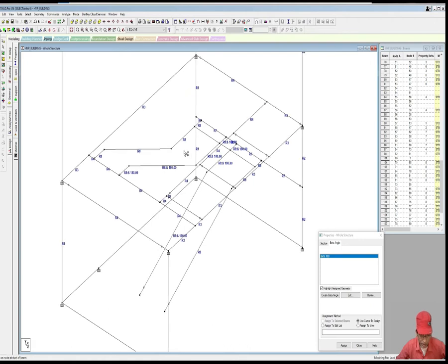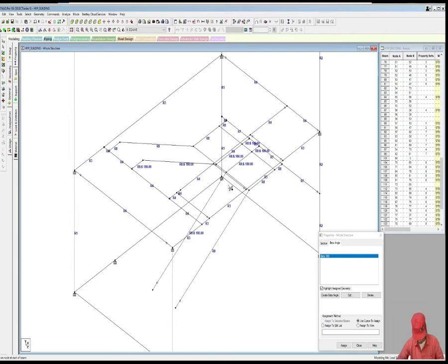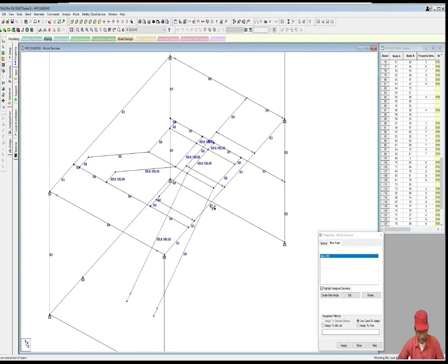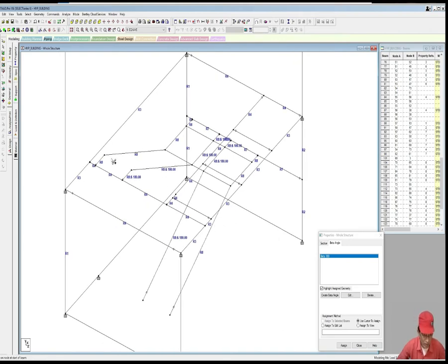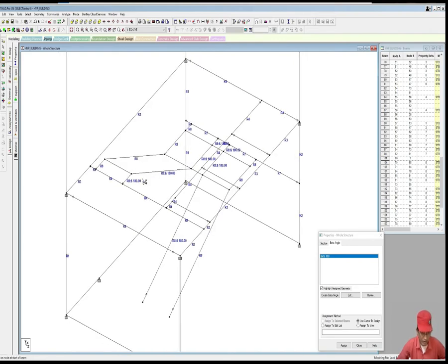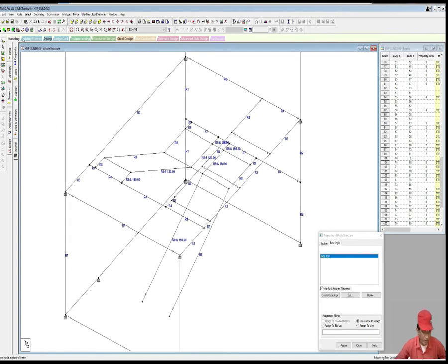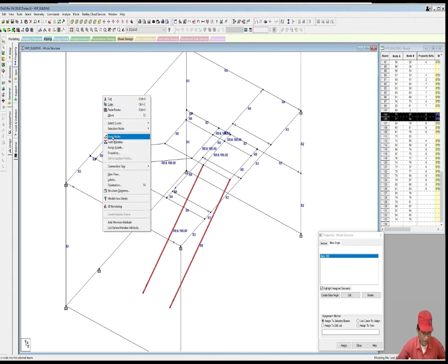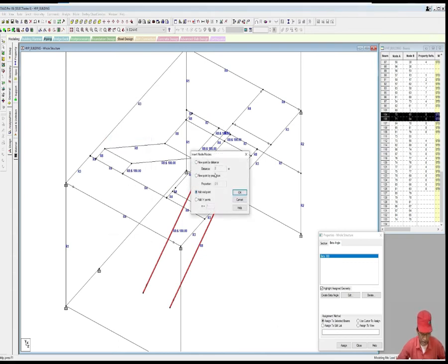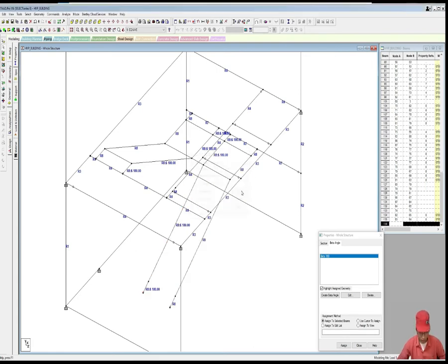We join these members. You can move the position of the staircase bit by bit, rotate the model bit by bit by using arrow keys. So we select, again we insert some node here, copy, copy, insert node, add a distance 0.3. Okay.